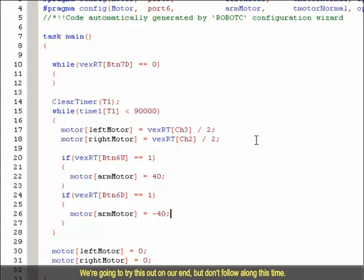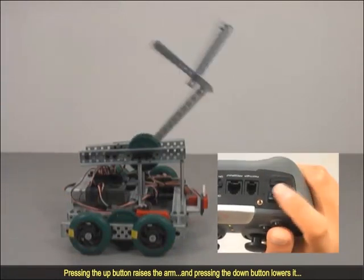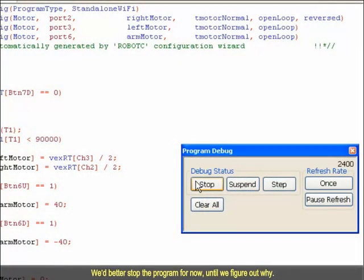We're going to try this out on our end, but don't follow along this time. Even though the code may seem complete, you'll see in a moment it's missing a key component. Pressing the up button raises the arm, and pressing the down button lowers it, but the arm won't stop, even when we let go of the buttons. We'd better stop the program for now, until we figure out why.